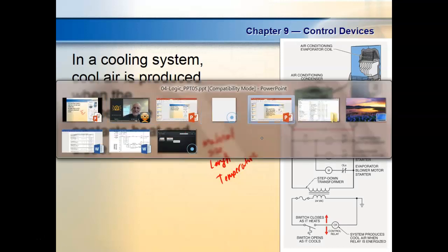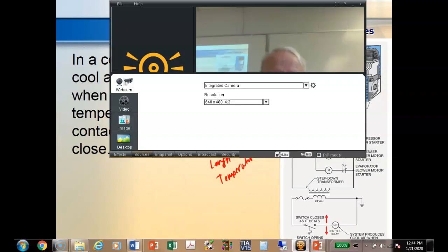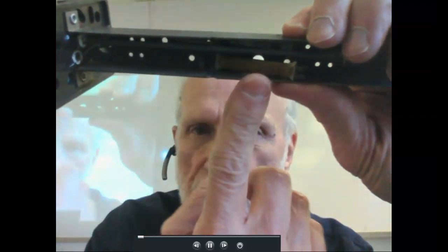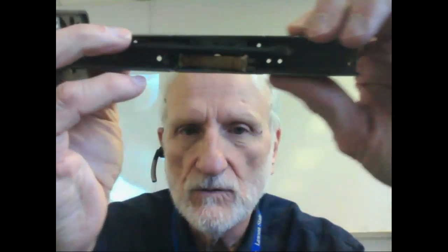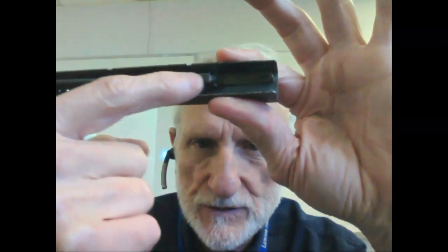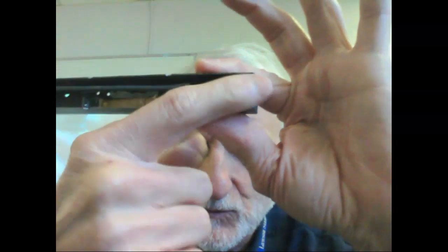And that's this guy right here. It's nothing but a bunch of coils of wire. It's an RTD, so this would give us an analog signal. This guy at the end that's bent up is a bimetallic temperature sensor, so it operates a switch. There's a switch back here in the back, but it's been bent.